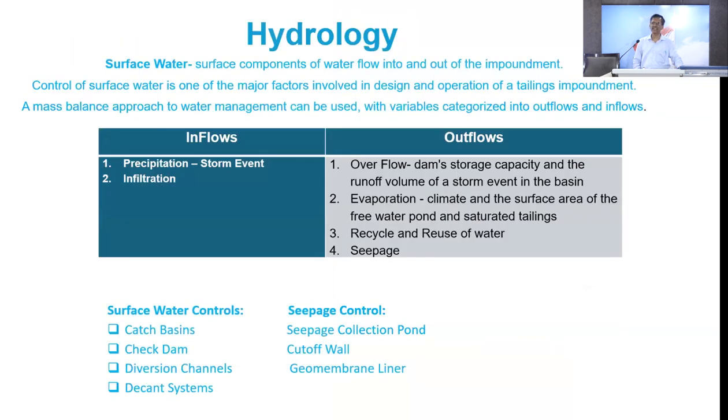Because if there really was water seepage, I could have drawn my phreatic line and seen that it's matching. That would mean the geomembrane is not working. But here it didn't show me that trend, rather it's showing me the water level at the outside.